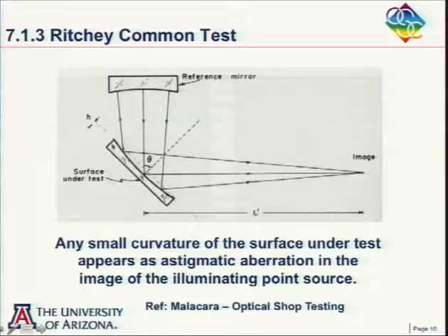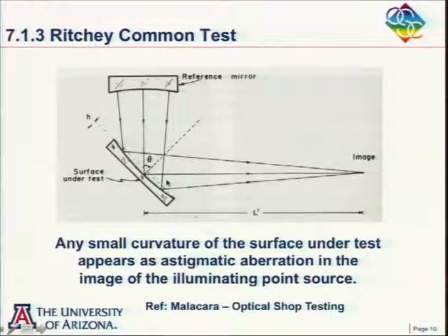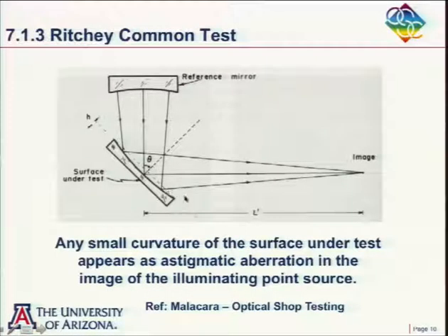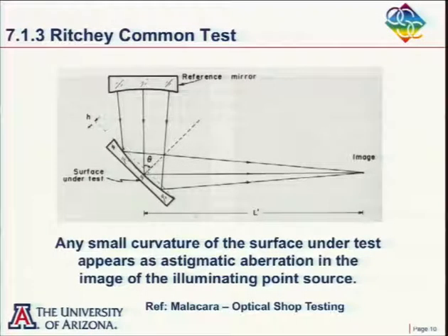And in fact, if you want to really be good about it, the angle of incidence varies over the sample here. Cosine theta varies, and so you might want to put that into your software too to correct for the variation in the angle of incidence. I mean, I'd use an interferometer for everything. That's my approach to life.